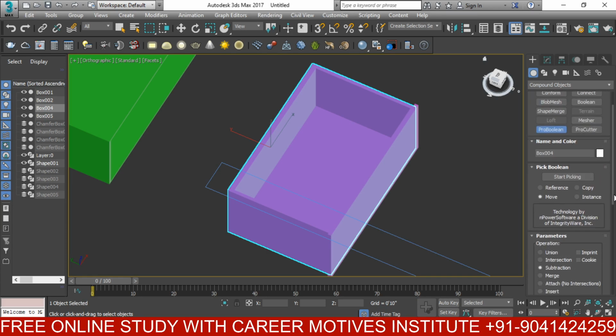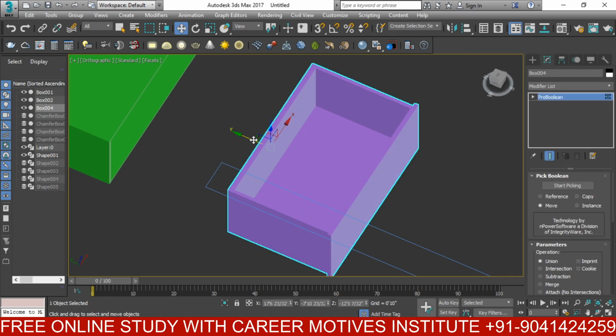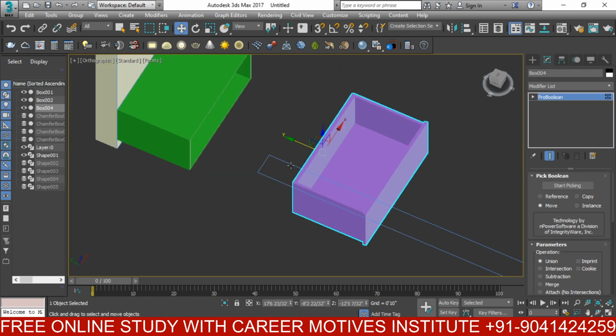Here is union, so I'm going to select union, start picking, and this, and now this body has become a single body. Look, the cover is completely attached with this drawer.